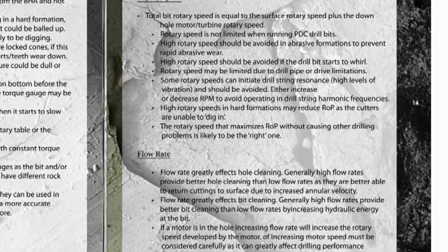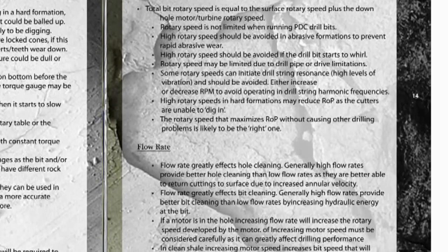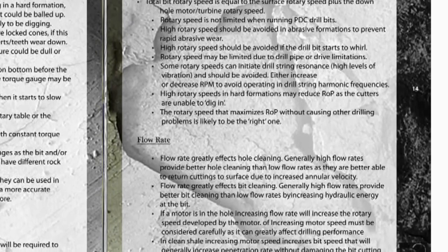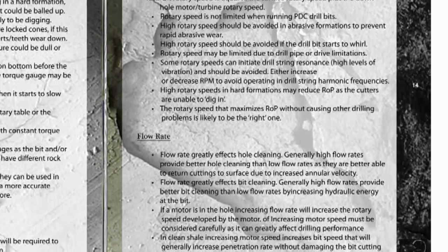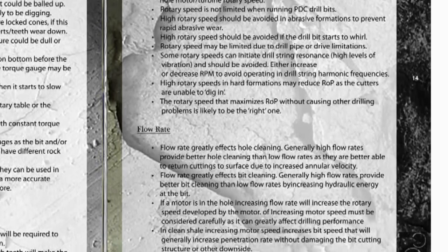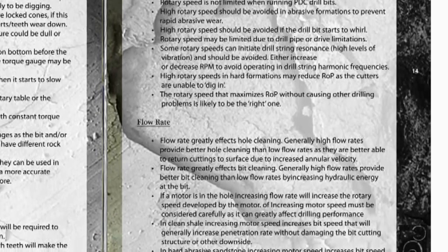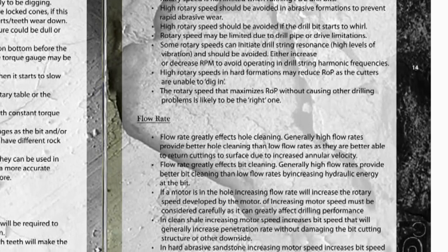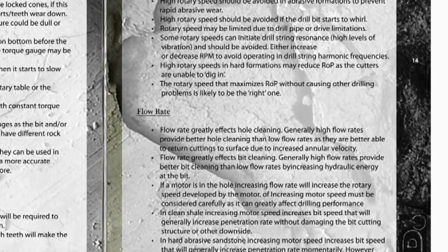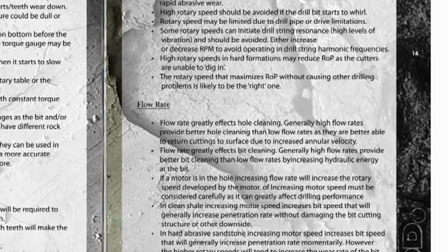Flow rate. Flow rate greatly affects hole cleaning. Generally, high flow rates provide better hole cleaning than low flow rates, as they are better able to return cuttings to surface due to increased annular velocity. Flow rate greatly affects bit cleaning. Generally, high flow rates provide better bit cleaning than low flow rates by increasing hydraulic energy at the bit. If a motor is in the hole, increasing flow rate will increase the rotary speed developed by the motor. Increasing motor speed must be considered carefully as it can greatly affect drilling performance.